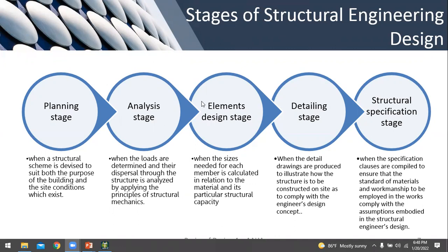When in the planning stage, we just sit at the desk and study what the problems are, what regulations have to be covered in terms of regulatory bodies, what the constraints on construction are, what structural materials you have to use, what the site constraints and site conditions are, and soil testing. All those things have to be covered in the planning stage.